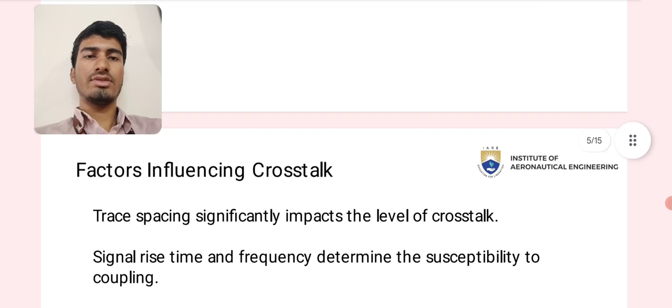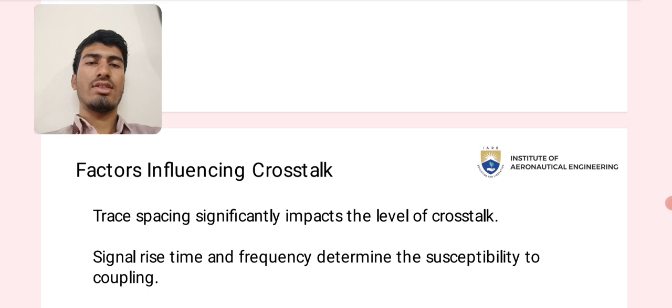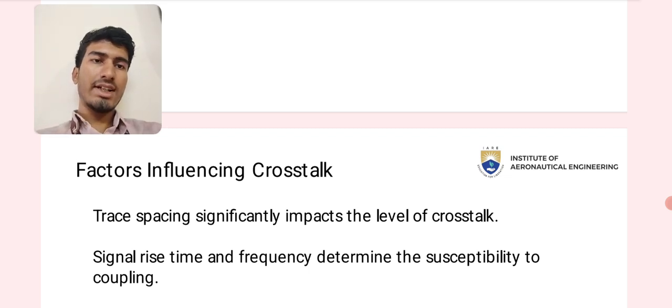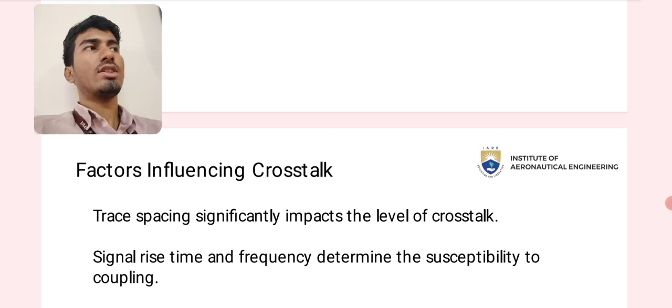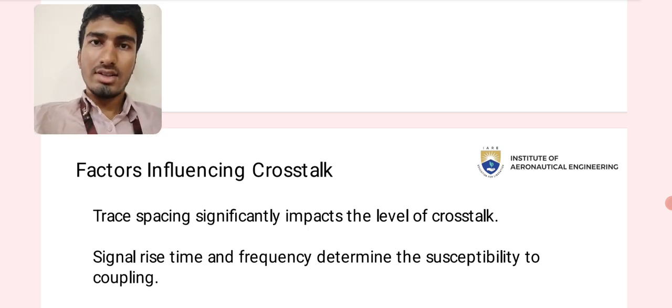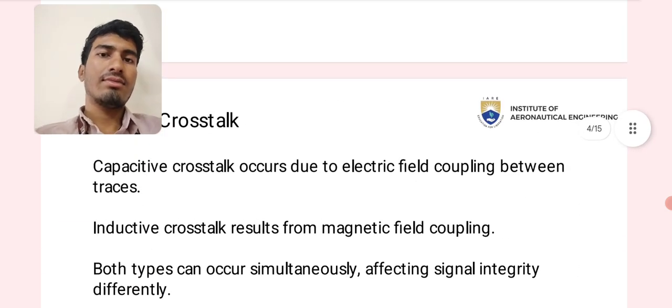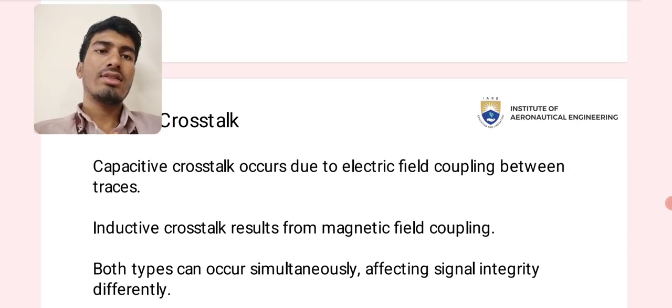Factors influencing crosstalk. The spacing of the traces significantly impacts the level of crosstalk, meaning electric fields significantly impact the coupling between two traces in the same PCB layout.